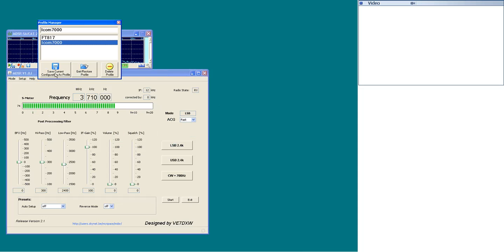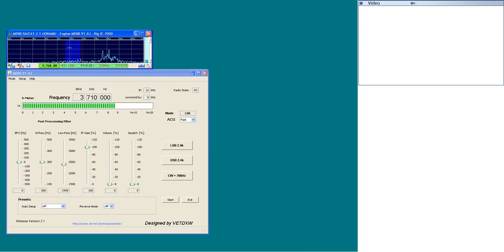Browse Bitmaps is used to view stored images of the spectrum display that have been saved by pressing the F2 key. Pressing F5 will copy the display onto the clipboard for use in other applications. Pressing F11 will run the MDSR engine, and pressing F12 will stop it. This feature can only be used if the automation settings are all unselected. We will get back to this feature later.